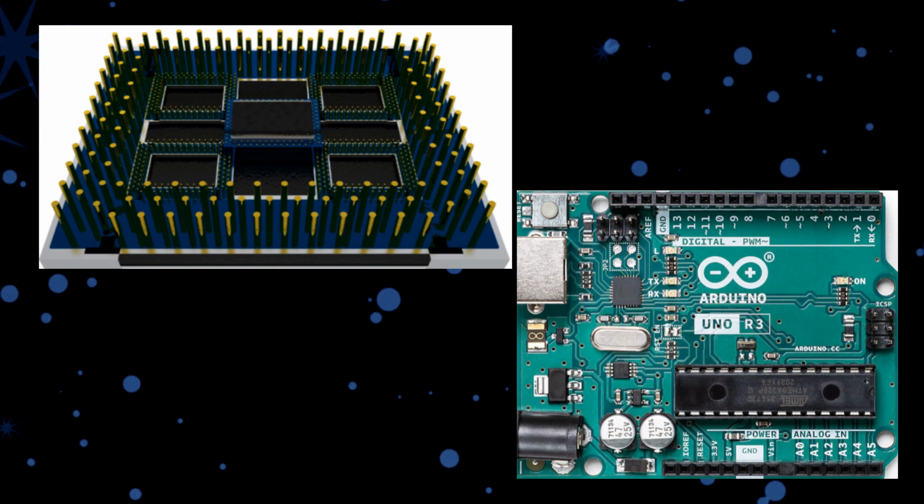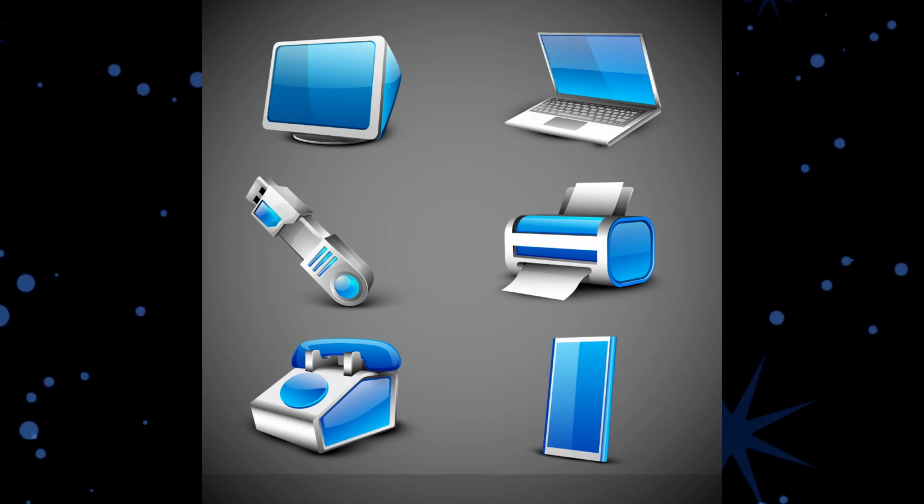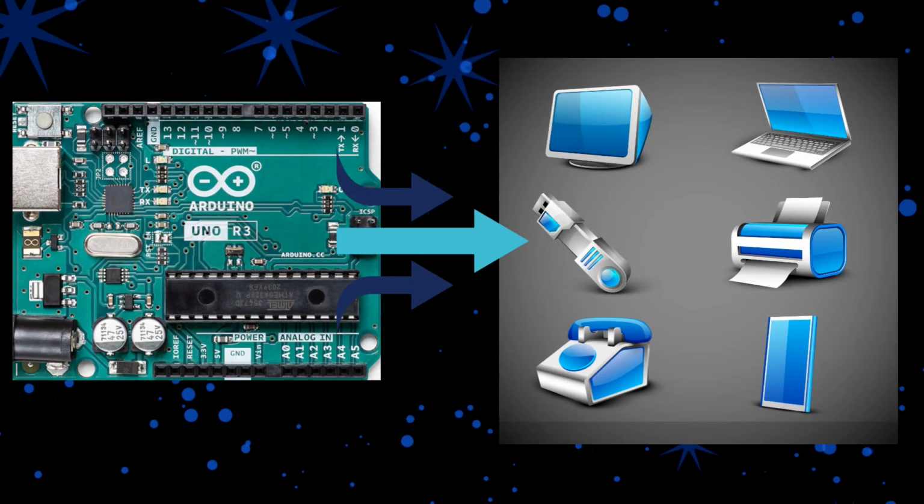The main device is something like the Arduino or a PC. The slave is a peripheral device controlled by the main device. I2Cs allow for multi-device communication, so the main device can communicate between several slave devices. For this reason, each device has a unique address. This lets the primary device select which secondary device it wants to send the data to.